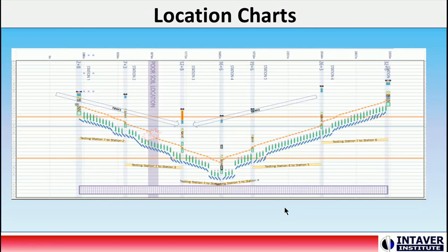In linear projects, activities are associated with certain locations. They are usually construction projects, such as buildings or roads, where each activity has location attributes in addition to the duration, start, and finish times of traditional project schedules. Location charts are a way of visualizing linear project schedules with locations on the horizontal axis and dates on the vertical axis.